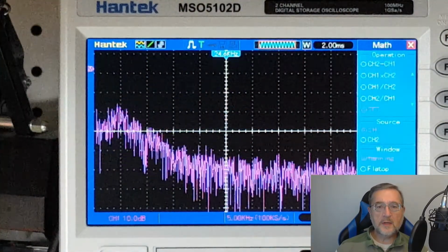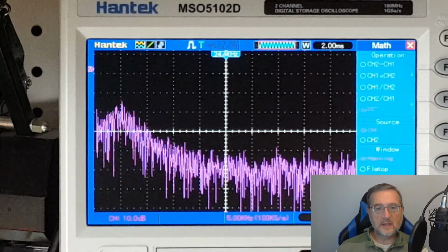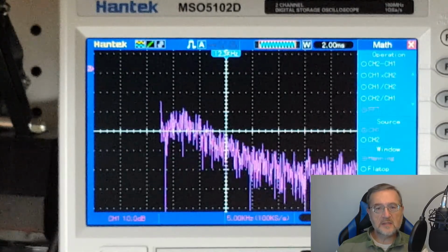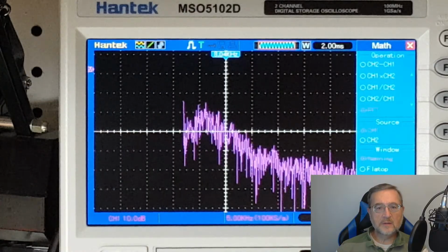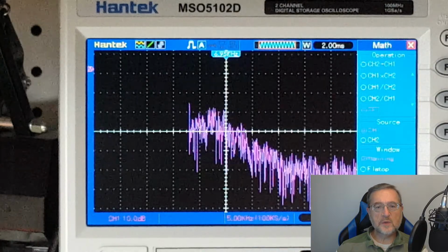region. So, if we now shift the image to the right until the center vertical line hits the 3 dB attenuation point, we can read on the horizontal axis the actual cutoff frequency, which seems about right around the 5 kHz we expected. And that proves that the filter does the job for which it was designed.